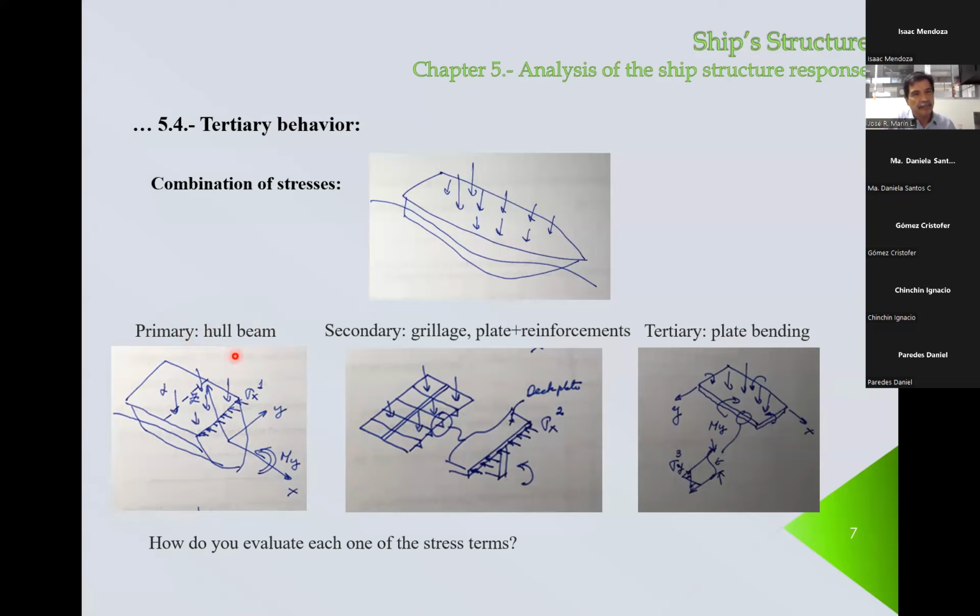It's very long. Very long, because you have many elements, right? So you have deck, side, bottom. It's possible, for example, for efficient vessels that the bottom is not flat, some inclination. And then you have longitudinal bulkheads, you have probably double bottom, then you have longitudinal stiffeners, so that's a lot of information.